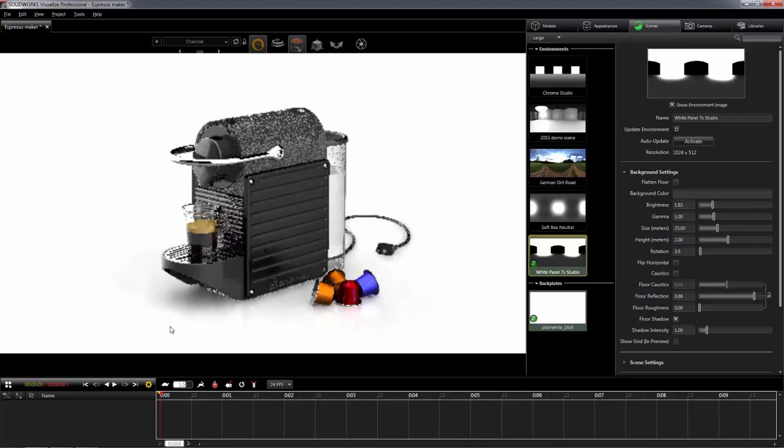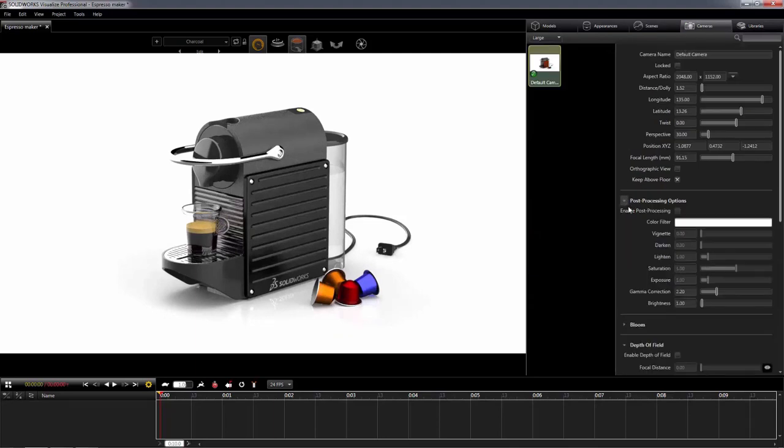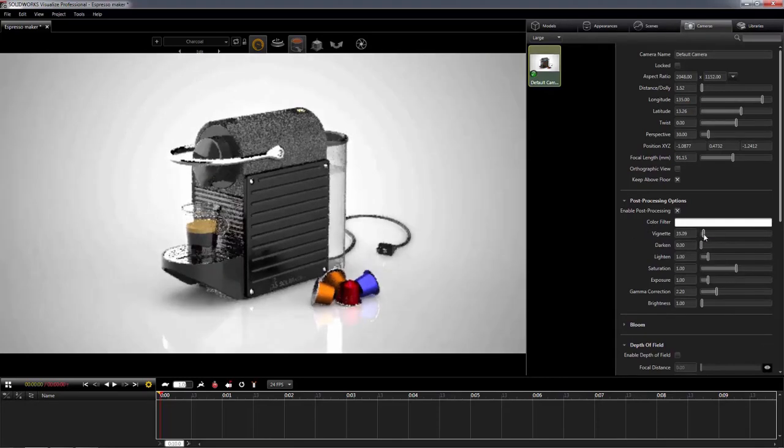Once you have everything set up, product, scene, and lighting, it's time to compose your shot. This is done in the Cameras tab, where you can make adjustments to the camera's depth of field, focal lengths, dolly position, etc. In addition, the power of SOLIDWORKS Visualize Professional is that it eliminates the need for post-processing photo editing software to complete your rendering, to add vignettes, adjust exposure compensations, increase or decrease lighting or darkness. It's all right within SOLIDWORKS Visualize Professional to drive focus towards your product. You no longer need another tool to achieve these powerful results.